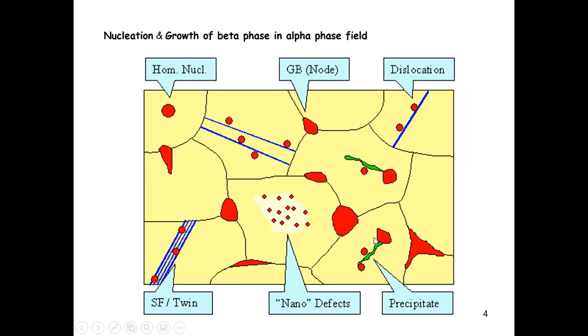But besides all of these, I think the next most commonly seen nucleation mechanism is nuclei formed on the grain boundary. Like this is a triple point, this is a binary, there's another triple point here, and here. Okay, so this is a schematic, but from this analysis there are two take-home points. Number one, homogeneous nucleation is very rare in solid transformation. Number two, nucleation, or heterogeneous nucleation I'll say, is significantly affected by the existing defects in the solid structure of the alpha phase.